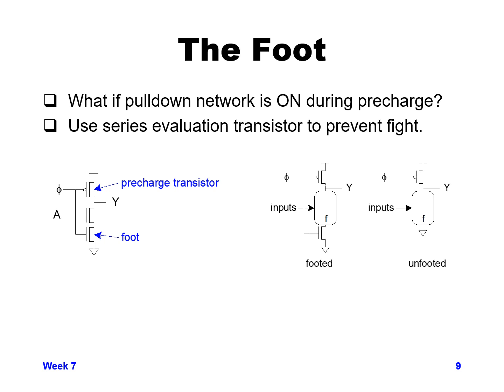Again, we get a fight between the pre-charge device, the PMOS that is being clocked, and our input value. We don't want this type of contention during pre-charge, and since we might not be 100% sure where our input is coming from, we don't necessarily know that it's going to be low for any random inputs coming in.